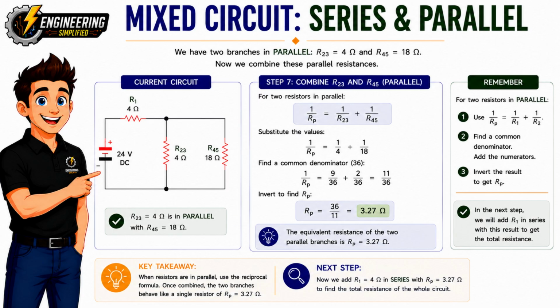To add these fractions, we need a common denominator. The lowest common denominator of 4 and 18 is 36. So 1/4 becomes 9 over 36, and 1/18 becomes 2 over 36. Adding them together gives us 11 over 36. Remember, this is still 1 over the equivalent resistance. So now we invert the fraction. R sub P equals 36 divided by 11, which equals approximately 3.27 ohms.